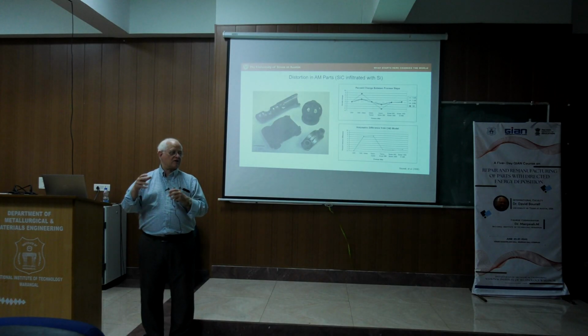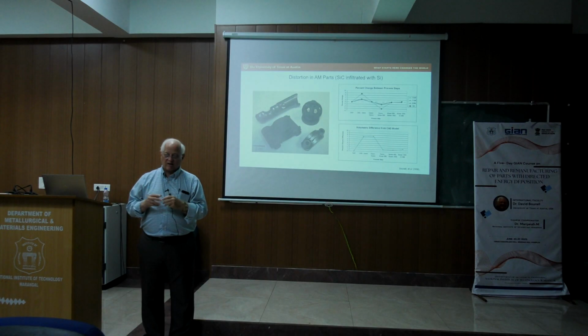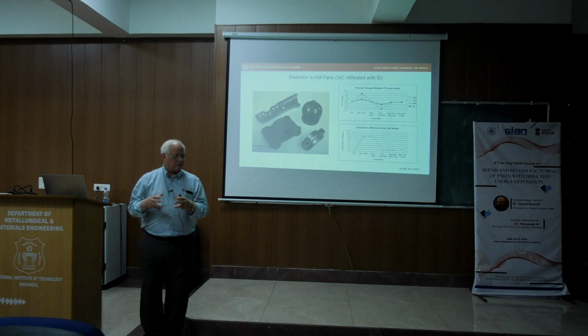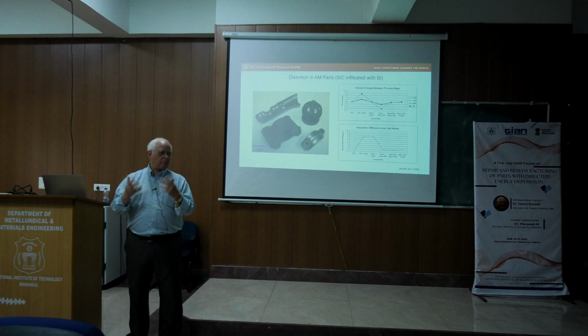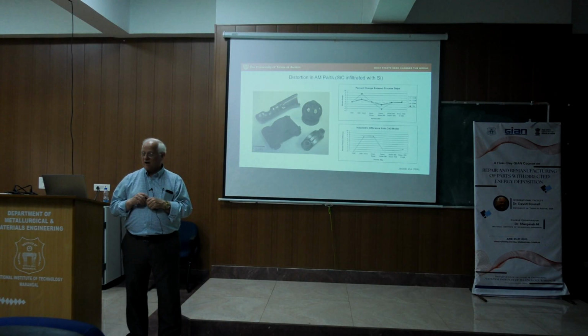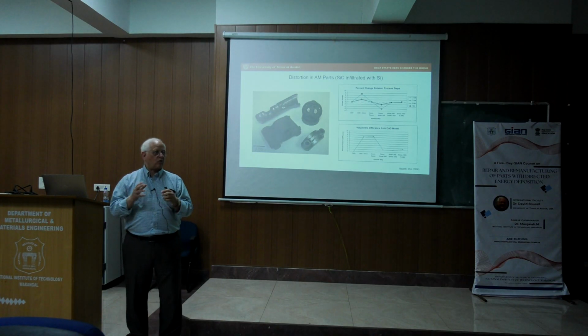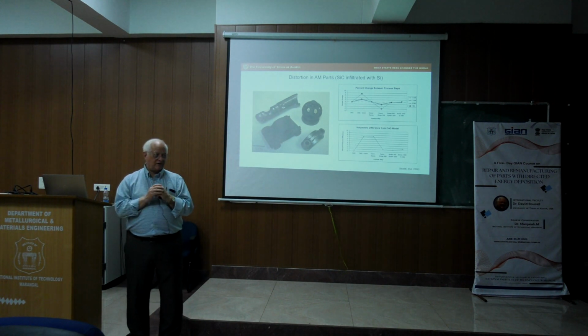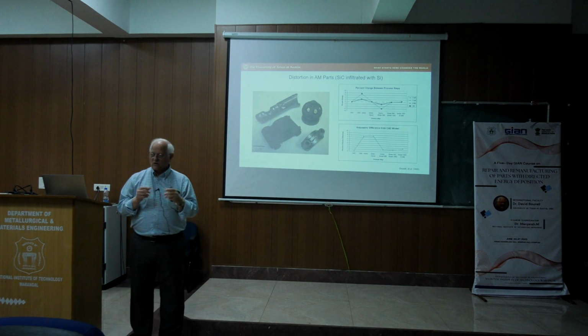The phenolic is a thermoset material, so it will cross-link, but the time in the chamber was insufficient for cross-linking to occur, so we simply melted and solidified the phenolic. So our green part is basically silicon carbide particles glued together with uncured phenolic. That's what we call the green part.